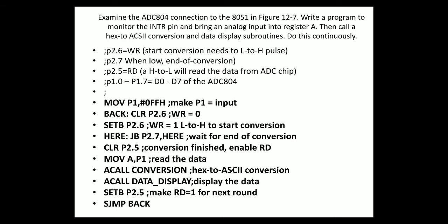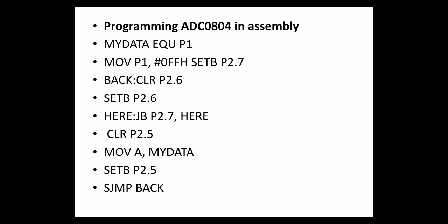I think everybody has understood what is being done. These are some basic fundamentals. If you know about the operation of these pins, namely WR, INTR, RD, and that data is available on port 1, if you know these four facts, then you can write a program for ADC 0804 in a very simple order. Let us see some more programs on this.